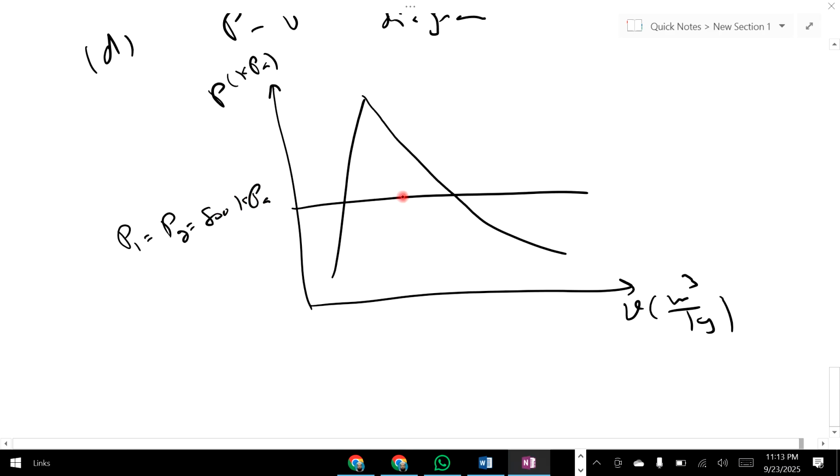Initially the water is a mixture of liquid and vapor. It means that the initial point is here, between the saturated liquid line and saturated vapor. Finally the steam is superheated at 350 degrees centigrade. So this is point 1, this is point 2. Constant pressure line is point 1 to 2. Here temperature is saturation temperature T1 is equal to 170.43 degrees centigrade. Here temperature T2 is equal to 350 degrees. So this is the PV diagram for the problem.